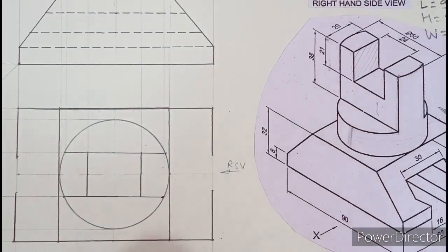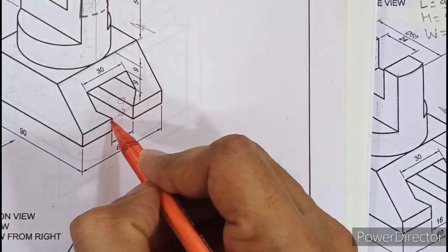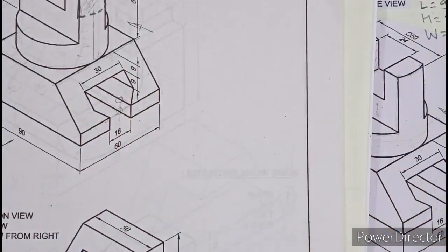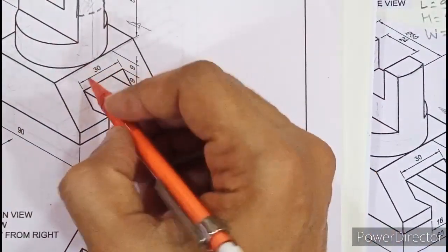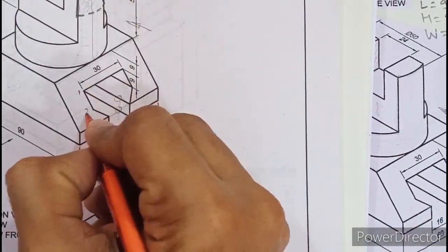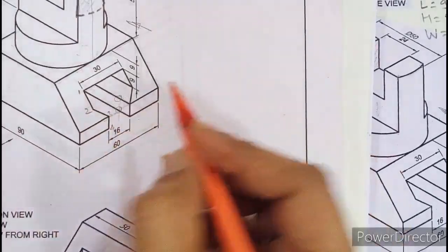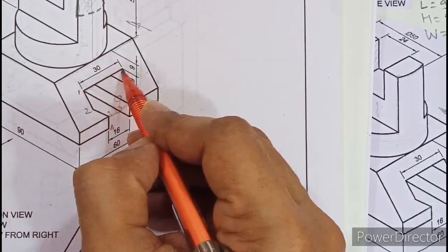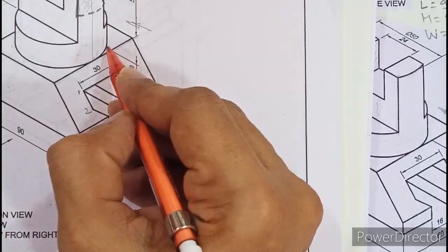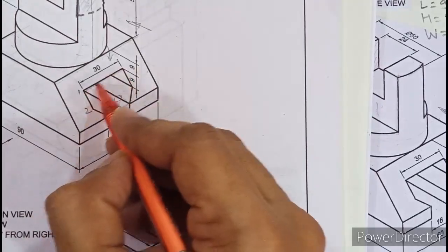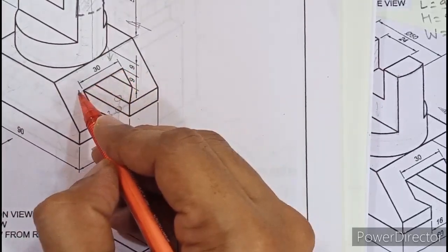After the platform is almost ready, the only thing left is to complete this incline slot. So this incline slot we need to draw. For this, what is essential is, see, this dimension is 30, right? And if I name this point as 1, 2, 3 for example, and this is 4. First of all, in the top view, you have to decide whether this 30 millimeter length of the line will be seen or not? The answer is yes, it will be seen, because this is inclined, and anything drawn on the incline will be seen. So this 30 mm length will be seen, and it corresponds to point number 1.